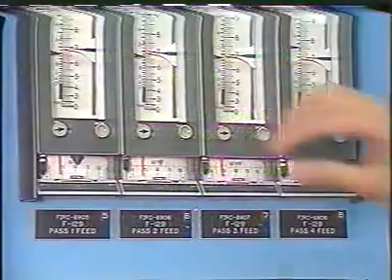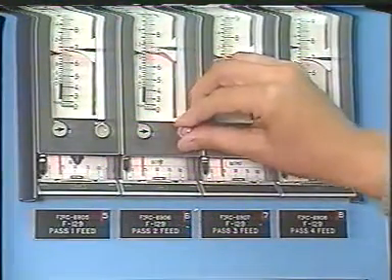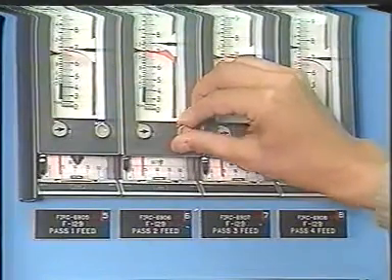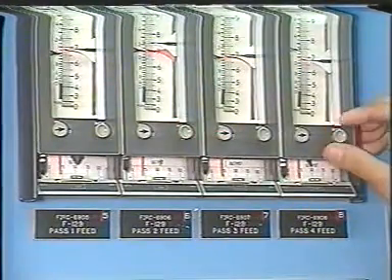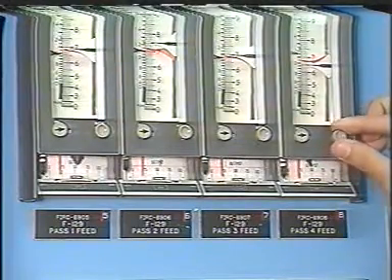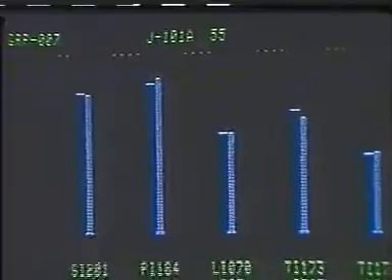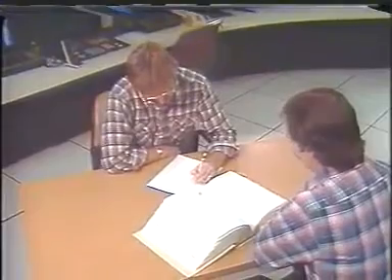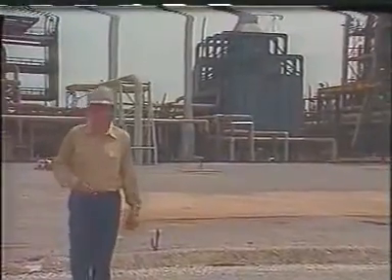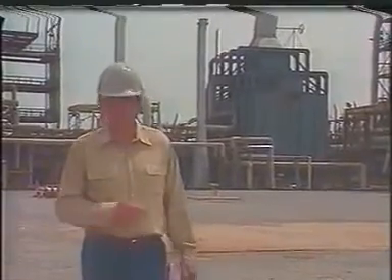At many controllers, a process pointer indicates the actual condition of the variable controlled by that controller, and another pointer indicates the set point value for which the controller is adjusted. On computer systems, the condition of the variable and its set point are often shown graphically. An operating manual or other operating instructions for each process unit should identify the set point for each variable in a particular process. So, the main job of a control loop is to keep a given process variable at its set point. And the set point for each variable is determined by what conditions will produce the desired end product.